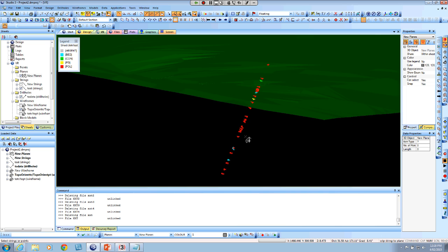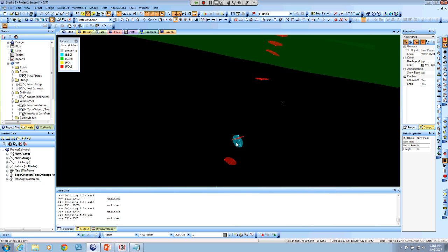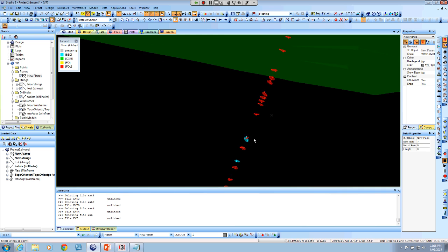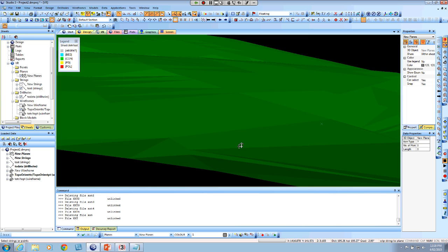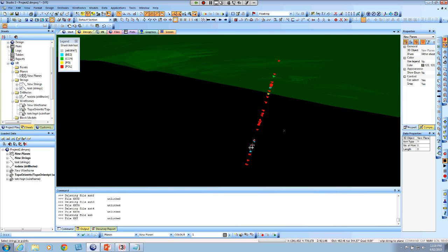down the drill hole. They look quite small, so if you want to make bedding larger, what we can do is change that in the file. And we can change that via an extra statement, which I think is important to do if you've got faults and you want to show the fault to be larger in size, so you can start linking them up between drill holes. So to do that, we've got this new file and it's called New Planes, and I'm just going to save this.